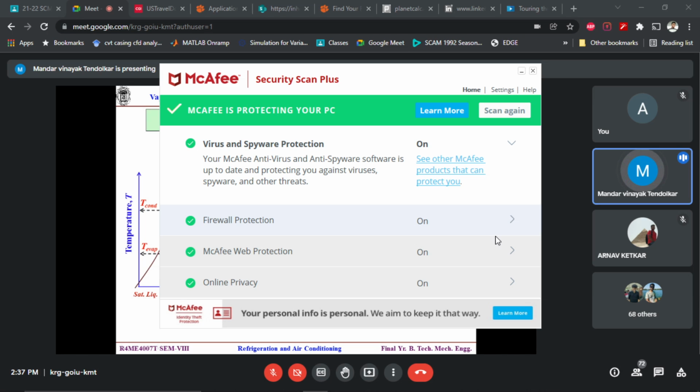Correct? So the Carnot cycle basic deviation over here, because of the sensible heat part, so no constant temperature. Then the nature of the expansion, in the Carnot it is isentropic, here it is isenthalpic. Enthalpy remains same, so naturally entropy has to increase. Correct? And accordingly there will be extra part for this.